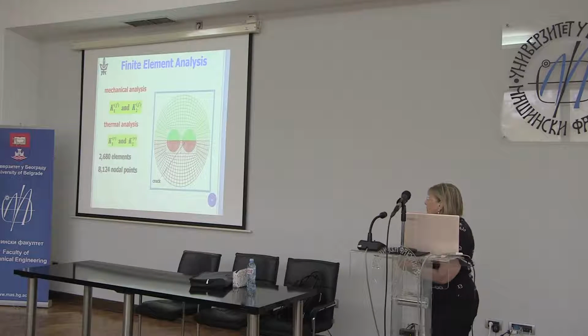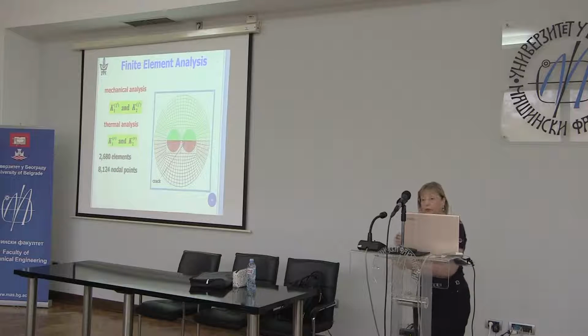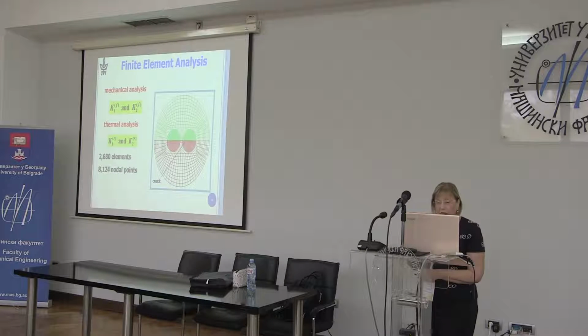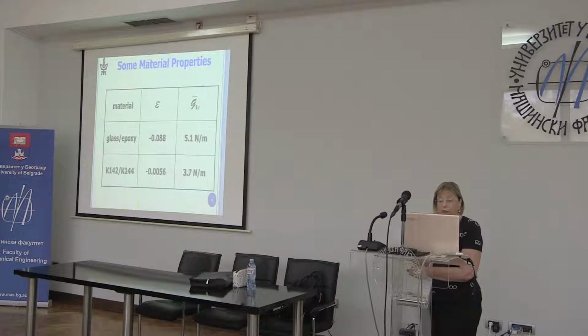And we found K1F and K2F due to applied loading. And we did a thermal analysis to find the residual Ks, and we superposed them so that we have a total stress intensity factor. KT1 is the total stress intensity factor, both due to applied load and residual curing stresses. And same thing for K2.